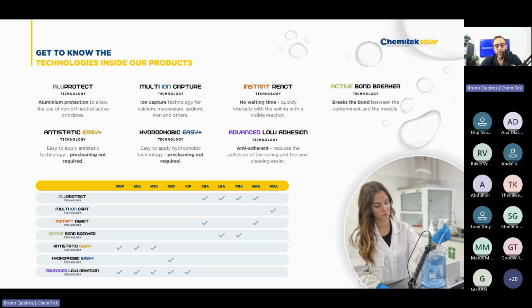So by applying a coating, you can reduce that adhesion during a longer period of time, and hopefully set up a cleaning schedule in between that can avoid the need of always using a specialized cleaning agent to remove that contaminant. By using a coating, you should be able to clean the plant for 3, 4, 5 times before you need to reapply the specialized cleaning agent to get the contaminant out.